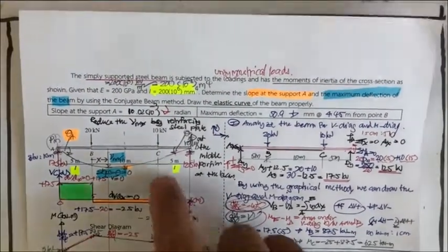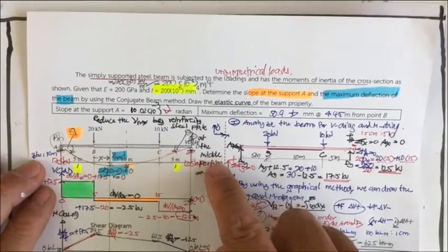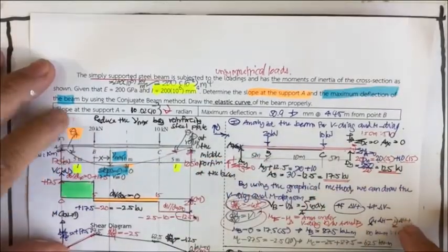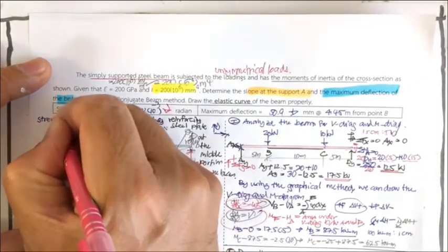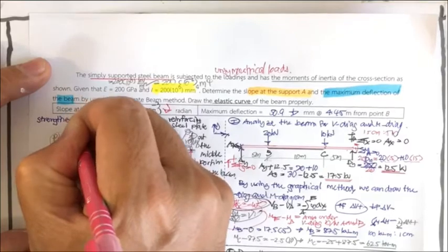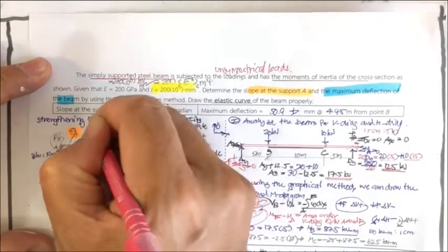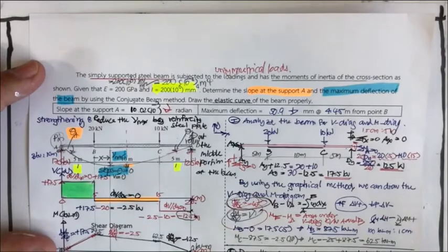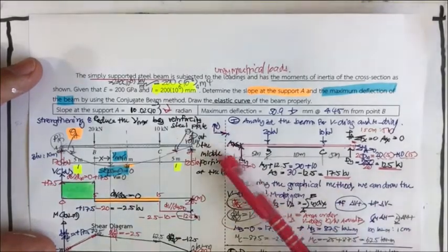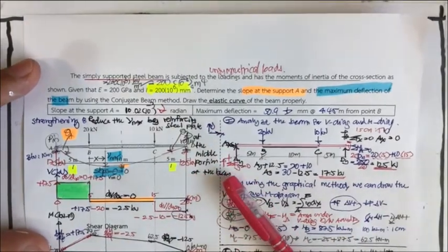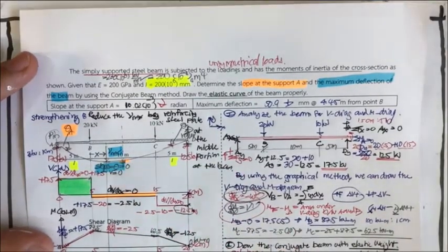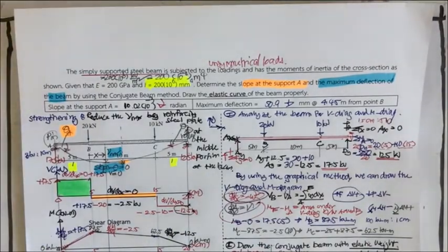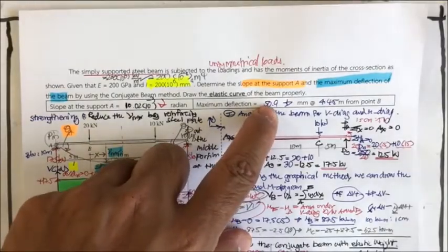and you may have some understanding of what we have to show for the beam with different EI, and the real application is about strengthening the beam. It's called strengthening beam by reducing the maximum deflection by reinforcing the steel plate at the middle portion of the beam. And if you like, you may take this portion to be the EI, and you do the same calculation. It's going to be a lot easier, and then you will get for sure larger maximum deflection than here.